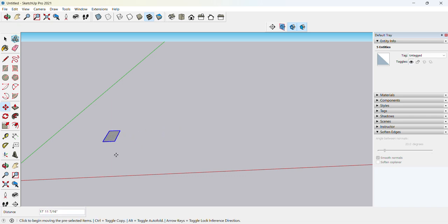So for that, first what I am doing, I just want to select the base point and click on control in keyboard. Clear? So this is one of the processes to take a single copy. And same as well, if you want to specify the distance for the copy also, you can. Base point. So specify the distance I am giving is 10 feet, like this. Otherwise, if you want the